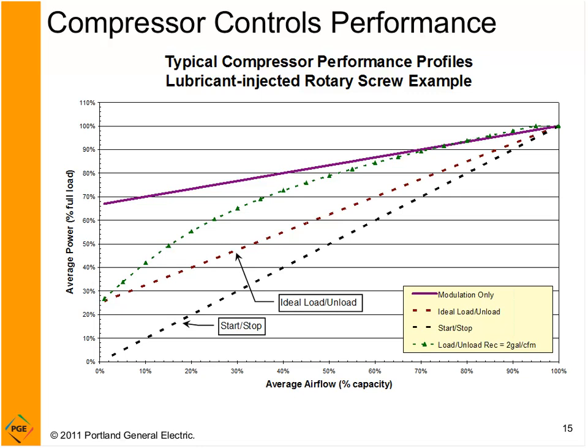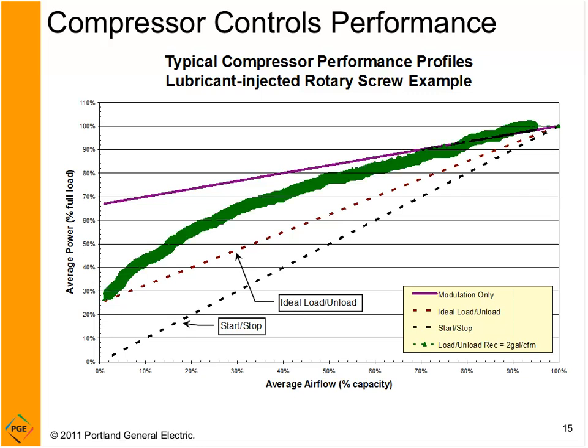As you might imagine, the compressor loads and unloads against a system volume. So if you have an air tank, you have to have some volume. It's just like your tire. If the tire had no volume at all, like these little skinny bike tires, it doesn't take any time at all to pump them up. But if you had a really, really big tire, then it takes a while to pump it up. So the more storage you have, the longer it takes to fill up, but more importantly, the longer it takes for the system to drain down.